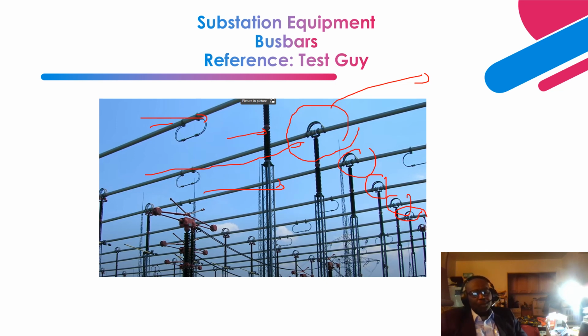Like I indicated, once the discipline electrical engineer performs all the short circuit simulation studies based on the worst case scenario and determines the peak asymmetrical short circuit current, they provide that information to the civil engineer to design the tubular bus system to be able to withstand the electrodynamic forces resulting from short circuit flow. So the tubular bus is designed in a rigid configuration, very rigid.